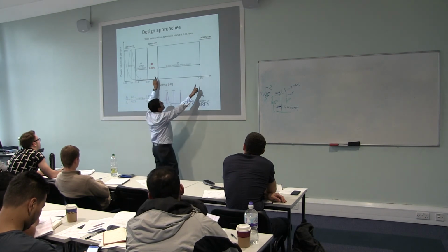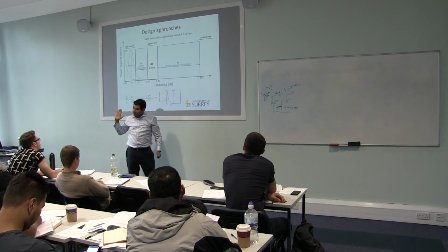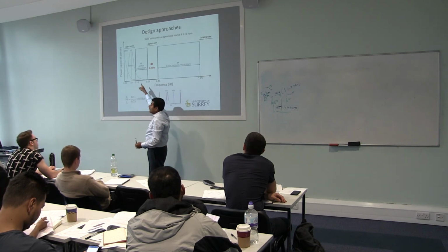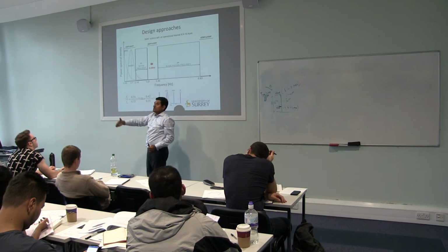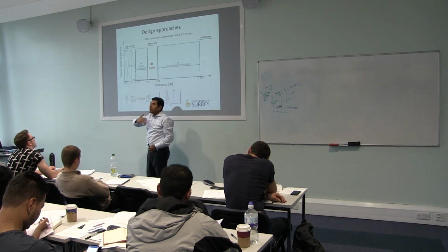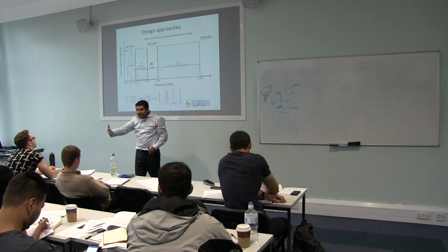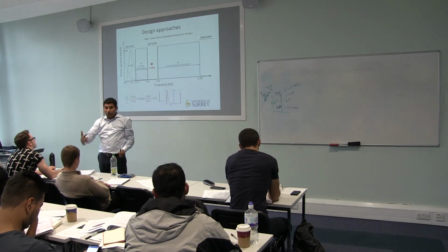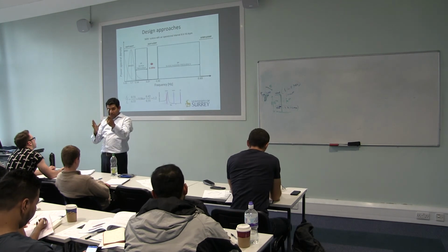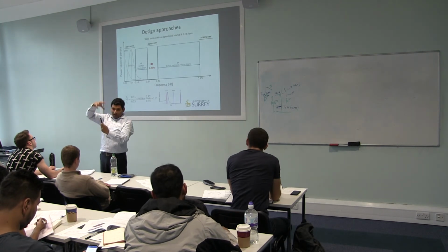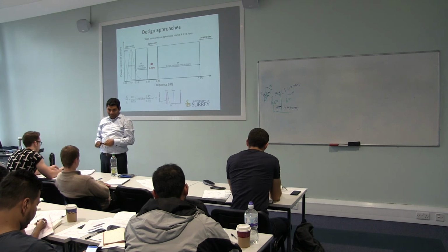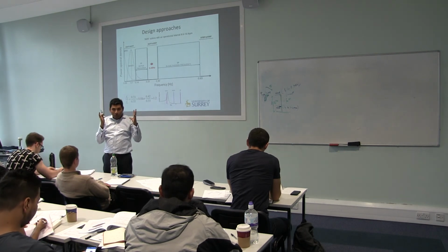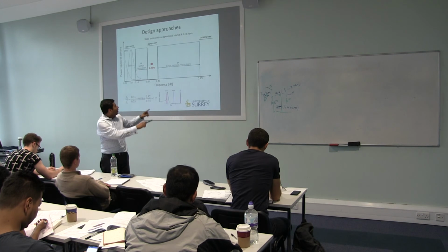That is the 3P. That means this big load, small load, big load, small load. So these are all cyclic loads, coming in periodically. They are applying some cyclic, dynamic load to your wind turbine, like a flagpole with a massive charge.